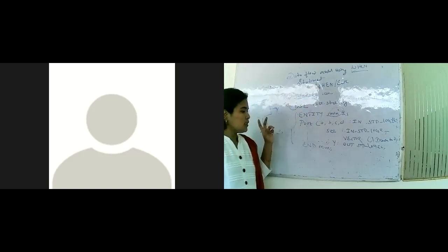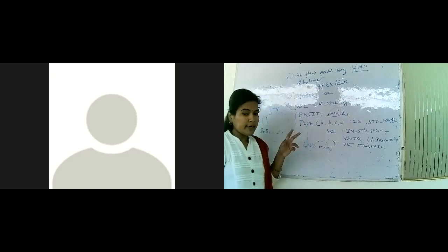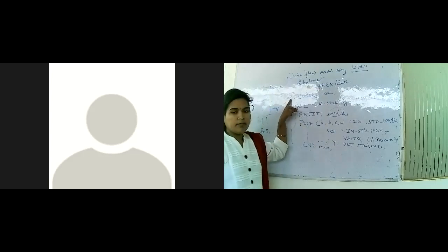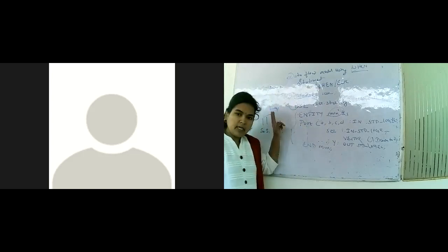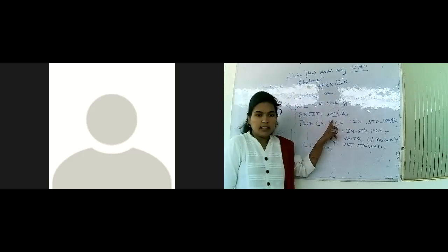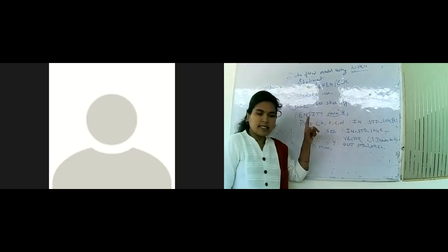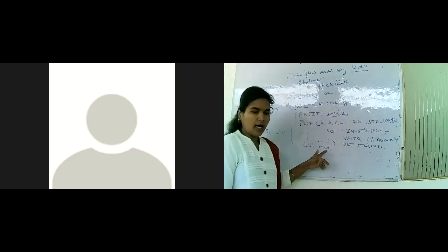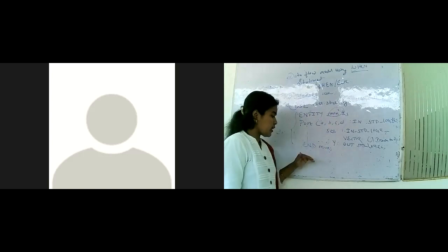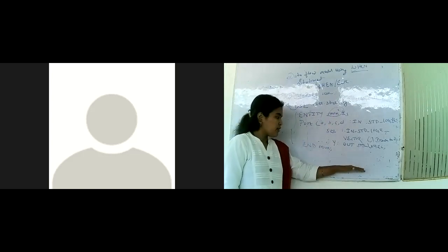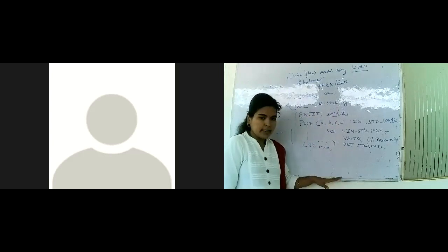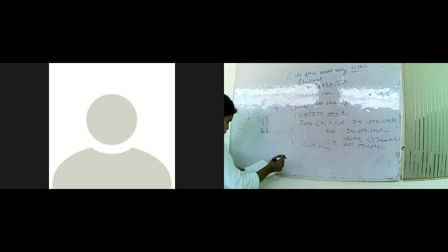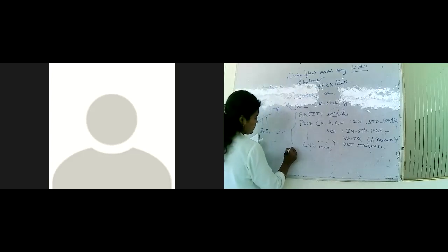To express the library, we are using two lines, library and use. Then we come to the entity, where we explain only the inputs and the outputs. That completes the entity module. Next one is architecture. We will represent the whole design in the architecture. So how to write this? Architecture.